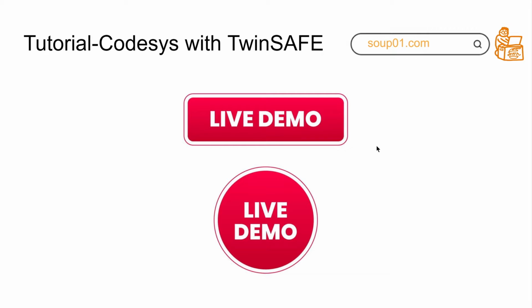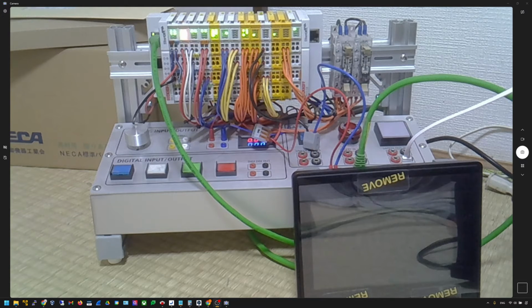Okay, I think my introduction here is enough. Now I turn on my camera and show you the hardware I'm using this time. Now here is the camera that I turned on, and you can see the hardware. The Codesys runtime I installed is inside this panel. It is a touch panel from EXA. The model number is EX707M, and here I use an Ethernet cable to connect the network from my EXA panel to the EtherCAT coupler from Beckhoff.